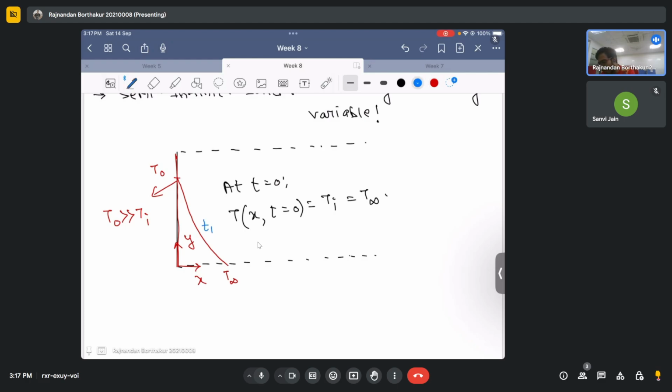So let's say I pick t1 to be equal to 2 seconds. This means that the disturbance, meaning the addition of this temperature that is prescribed on one face, will propagate up to a distance, let's say x1. So this distance I will consider as some x1. The physical meaning of this propagation is the conduction wave front, which is typically what is said in heat transfer language.